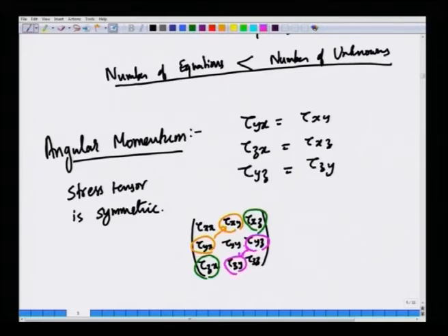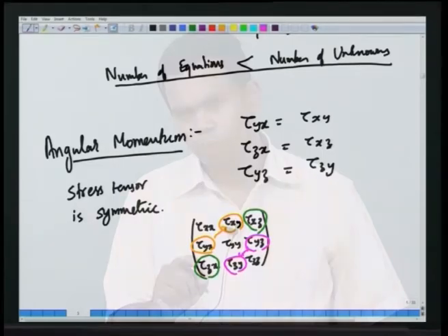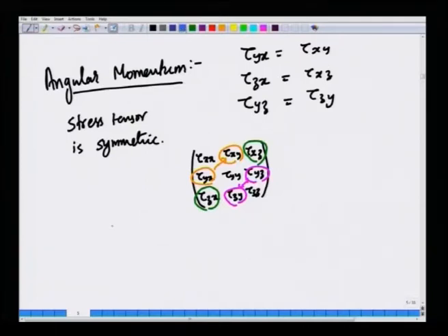Okay. They are the same because it turns out that when you do the angular momentum balance, and if there are no internal couples that generate angular momentum within the fluid, which is true for almost all fluids, then one can show that the stress tensor is identically symmetric always. So, we are left with only a symmetric matrix has only 6 elements, because there are 3 equalities that give you 3 additional equations. Therefore, a symmetric matrix has only 6 independent components as opposed to the 9 independent components for a second order tensor, 6 independent components.